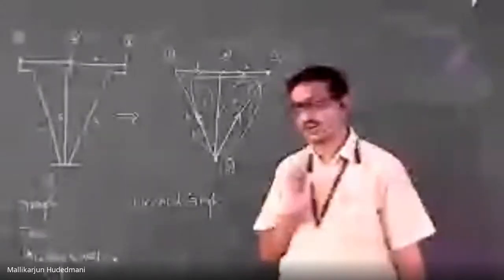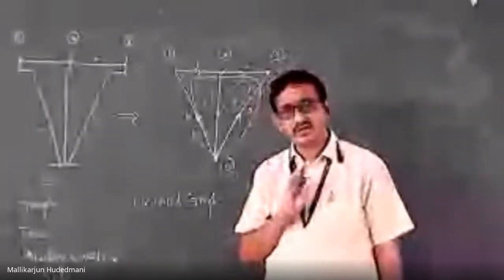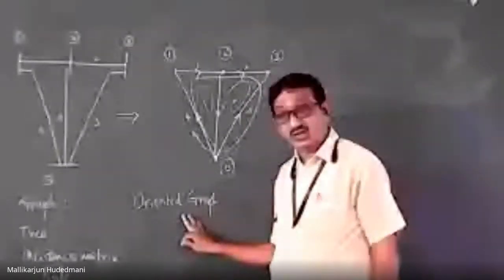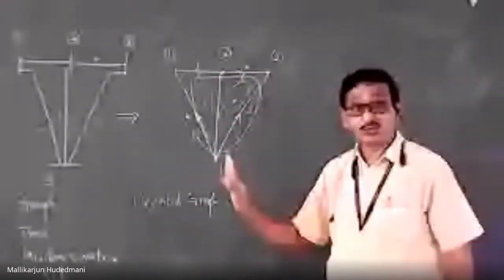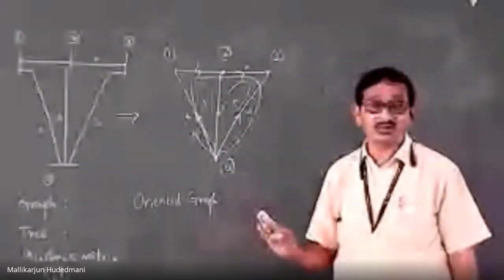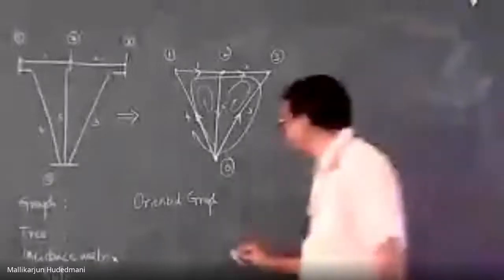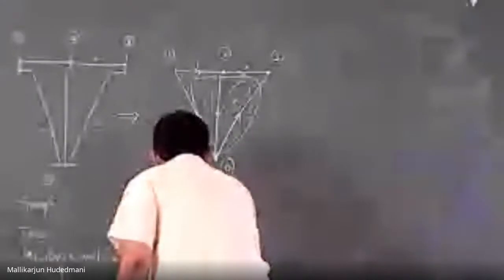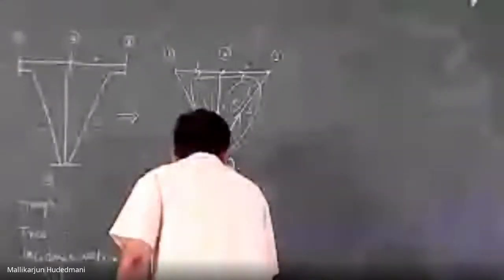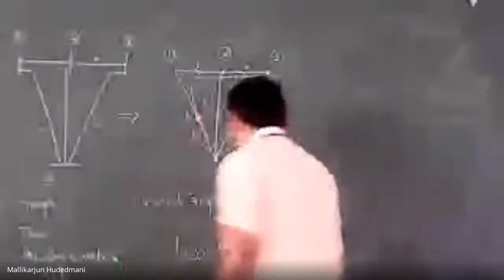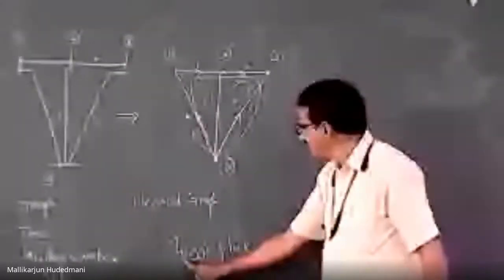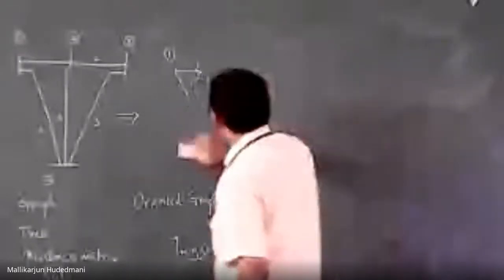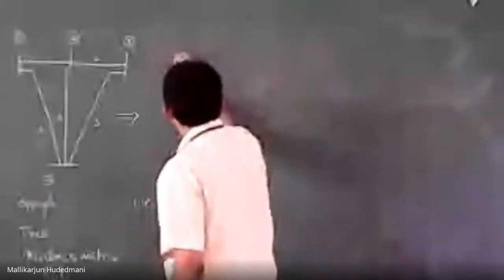Then question comes, how do you form a tree? Tree is obtained from a given graph by making some of the elements dotted, leaving remaining elements solid. Then comes elements called as twigs and links. Twigs and links. Some books refer branches and links. What is this? Let us make this again. I redraw it better, once again.